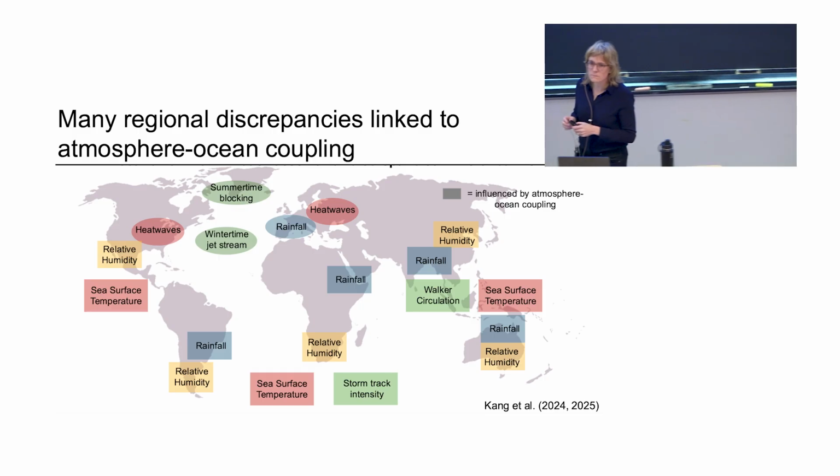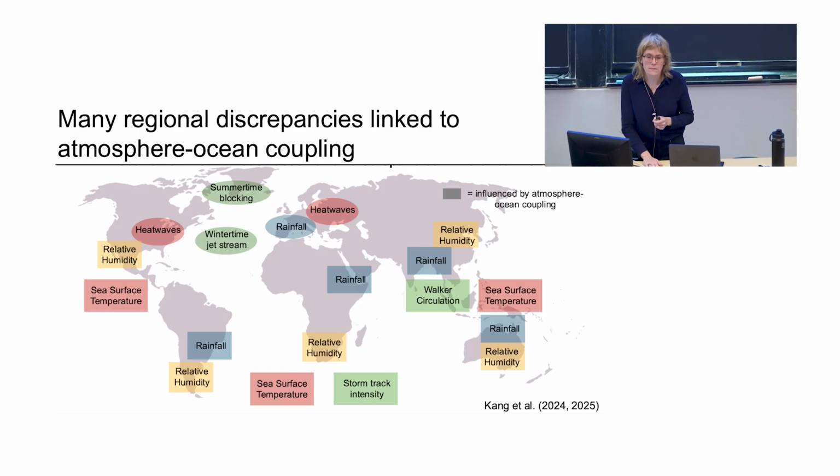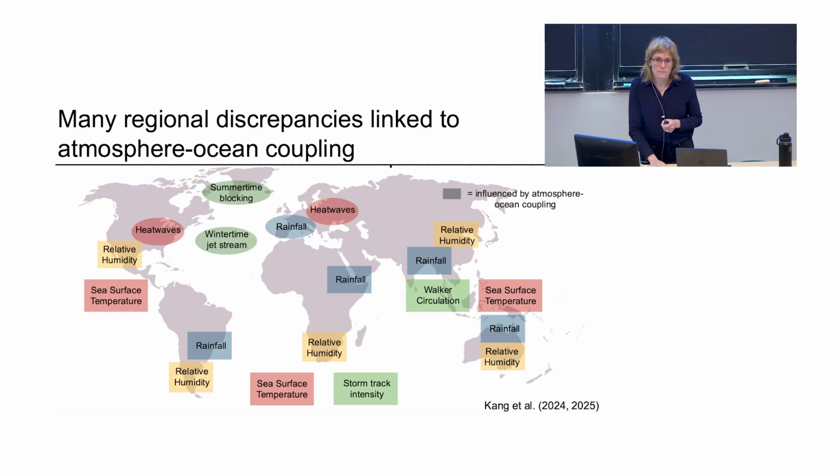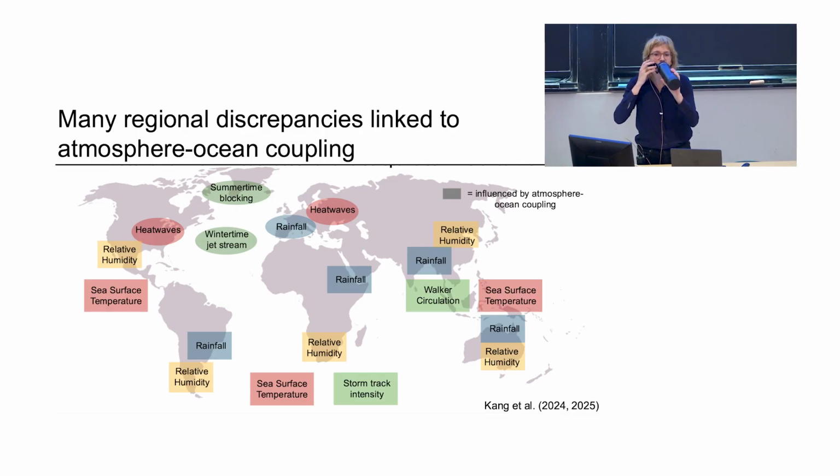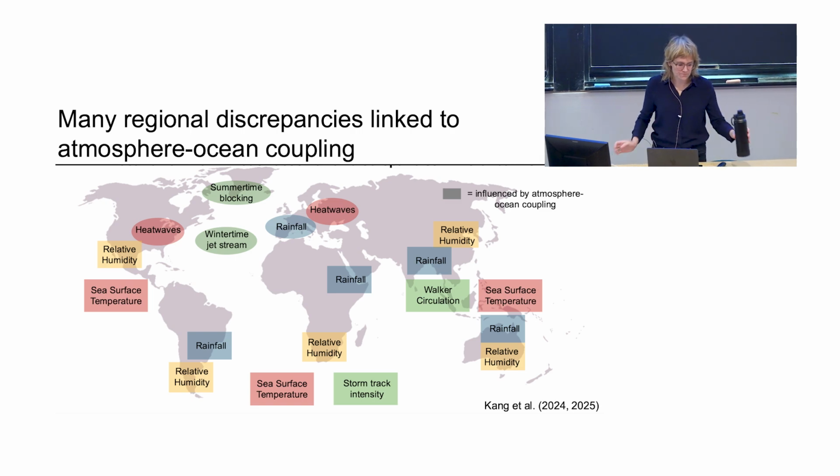Yeah. I'd like to understand how you're talking about the model that started. The thing that's there is, of course, time, and it's an initial value problem, and you're integrating time stepping forward with a certain grid size. Now, you said the way they started was to relate everything to temperature. So temperature was the main dependent variable. Have you got other dependent variables, or are you sticking with temperature as the overall thing in the evolution of these models?